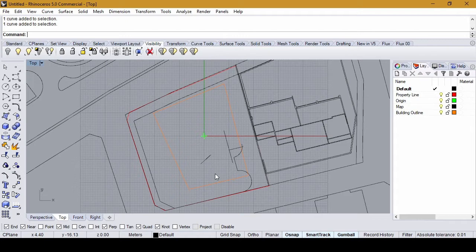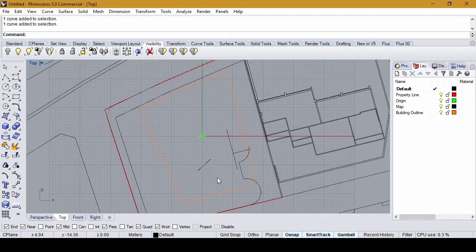So for simplicity reasons, basically in order to have a simple setup of modeling inside CAD and BIM, we want to rotate the entire world actually in order to be modeling the south and east facades along the X and Y axis of the site. As I said, not always is this necessary or even a good thing to do, but on this site, this is certainly beneficial for the design process.